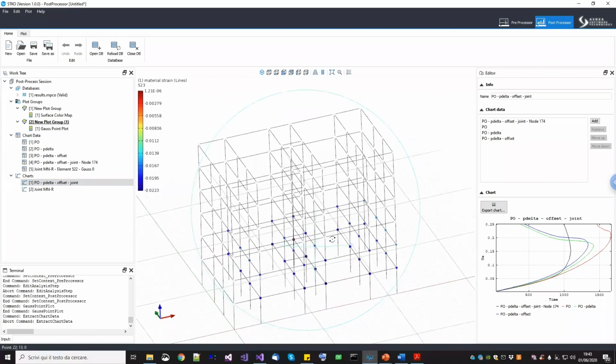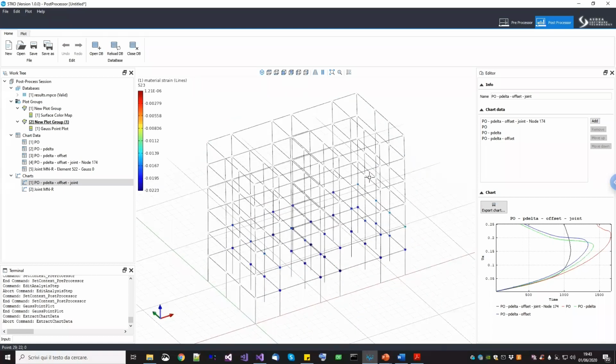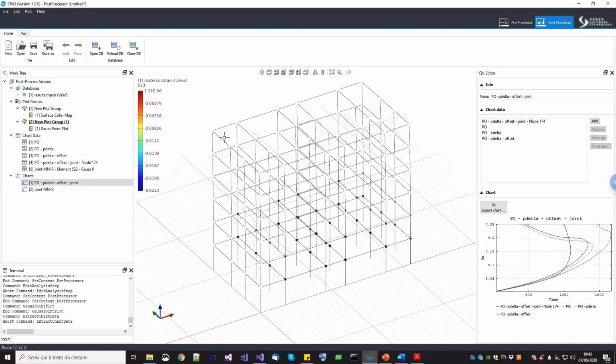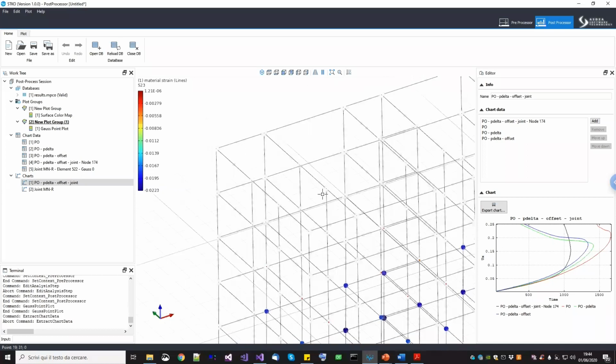of this tutorial. Okay, so basically in this tutorial you have seen how to start from a simple building, modeling this one in the CAD environment of STKO, how to start with a simple model using fiber cross sections for beams and columns, everything connected, and how to add nonlinearities and details one by one. So first of all, the rigid diaphragm, then how to remove the problem of the rigid diaphragm using either an axial release, as I told you in the previous webinar, or in this case, how to use the beam offset. Then I have shown you how to change from linear to P delta kinematics, and finally, how to create rigid joints. And as you can see, using the automation tools that you have in STKO, and in fact, we are working a lot on that, can speed up the modeling a lot.